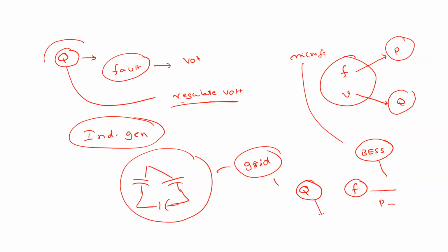Similarly, if you have reactive power fluctuation or voltage fluctuations, the same battery energy storage system operates in STATCOM mode, regulating the voltage across a particular bus by injecting the required amount of reactive power. So this active and reactive power control is compulsory, especially in transmission applications or microgrid applications. It is mostly achieved by using a battery energy storage system, or sometimes we use UPS.